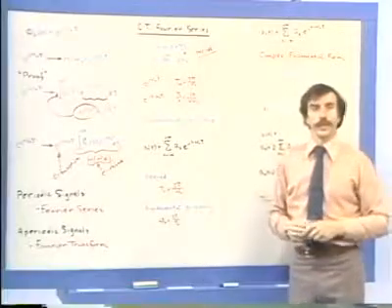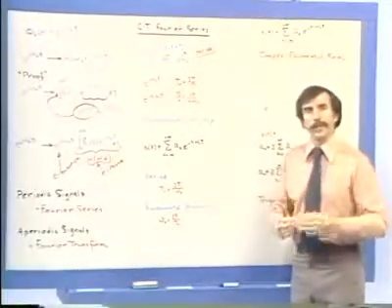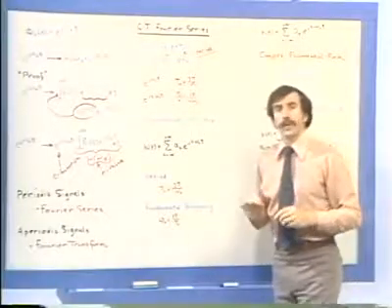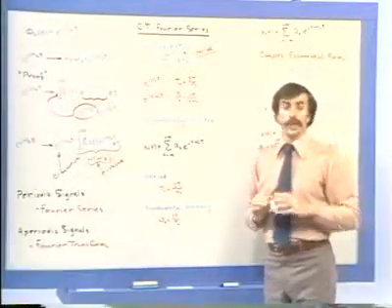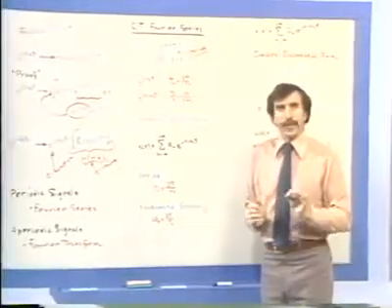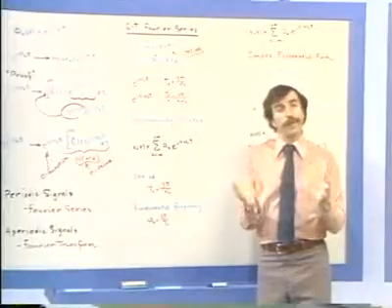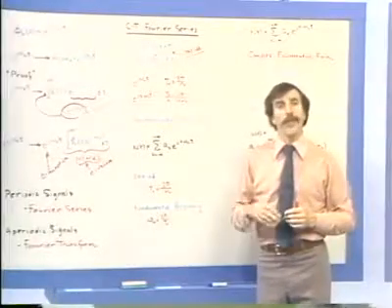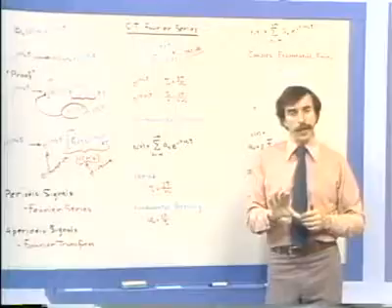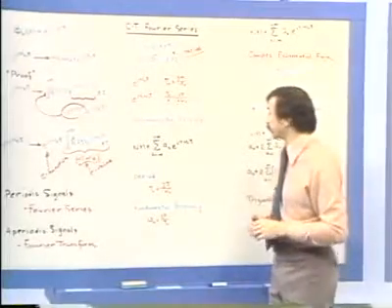Now, what the Fourier series says, and we'll justify this bit by bit as the discussion goes on, and in fact what Fourier said, which was essentially his brilliant insight, is that if I have a very general periodic signal, I can represent it as a linear combination of these harmonically related complex exponentials.